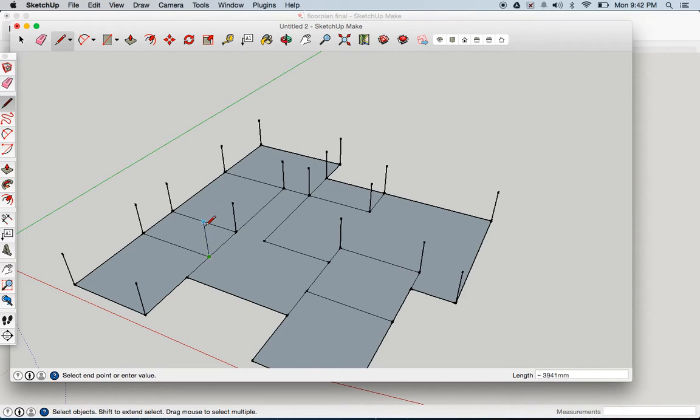Once you've drawn the vertical blue lines, you are then going to use these to generate your walls. Sometimes you'll notice I've got a clash with another line that wants to snap to that other line. If this happens, just draw the line way too long and type in your 2.5 again. Oops, 2.5, sorry, I need to redo that one.